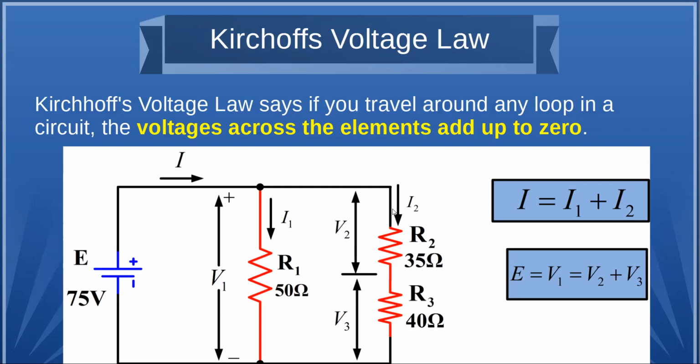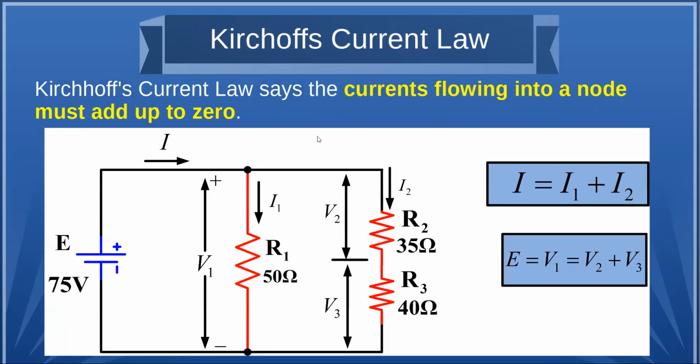And this was also showing that the current through these two resistors is going to be the same because they're in series. Now, over here, we have the current law, so we have a node at this point. I have a current I going into this node, and I have a current I1 coming out and I2 coming out. So those will equal this one, so it's zero.